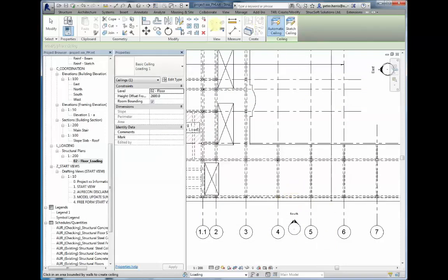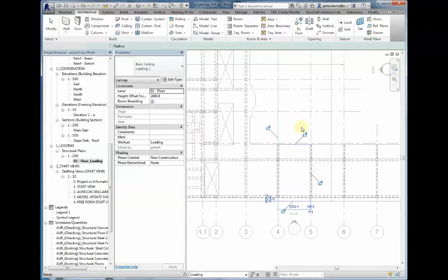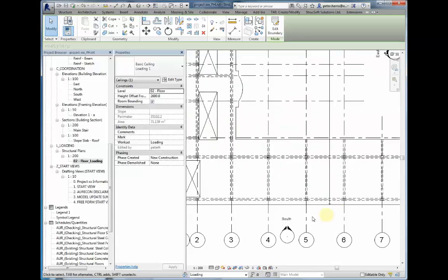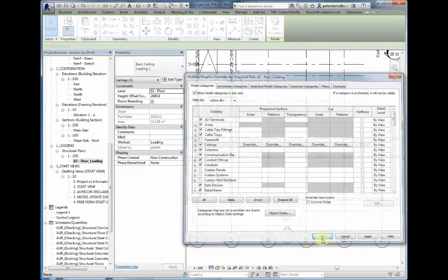At this point here, up towards top right, we would now want to sketch the ceiling. Again, in our sketch dialog box, just drawing ourselves a zone. Green tick for finish. At this point here, if you can't see anything, you need to now actively go and check your Visual Graphics overrides to ensure ceilings have been turned on. In this case here, they have not been turned on.